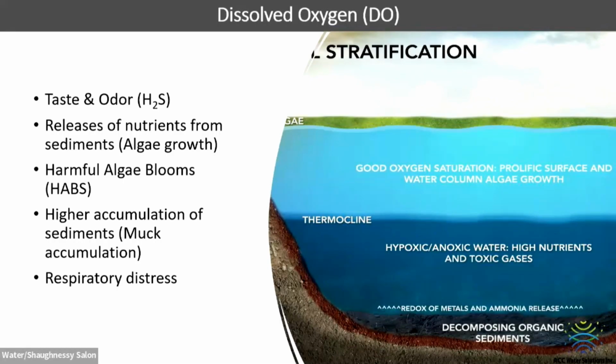So now we've got more nutrients coming out into the water column. So we've got phosphorus, which is a direct algal driver. We have reduced nitrogen species, starting with ammonia, which turns into nitrite and eventually nitrate. All of those things lead to productivity in ponds. And we end up with a cycle happening where you start off with a new pond and you get almost no algal growth.